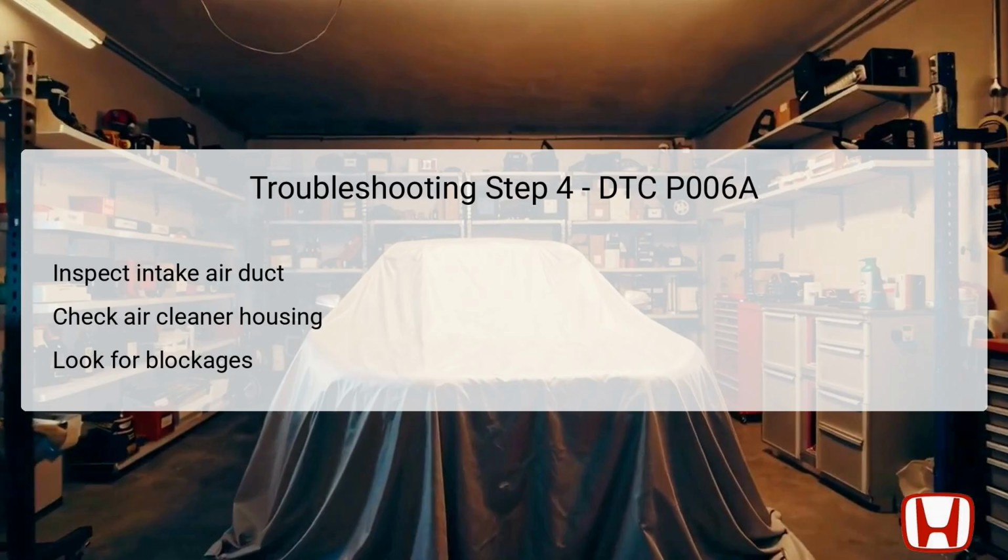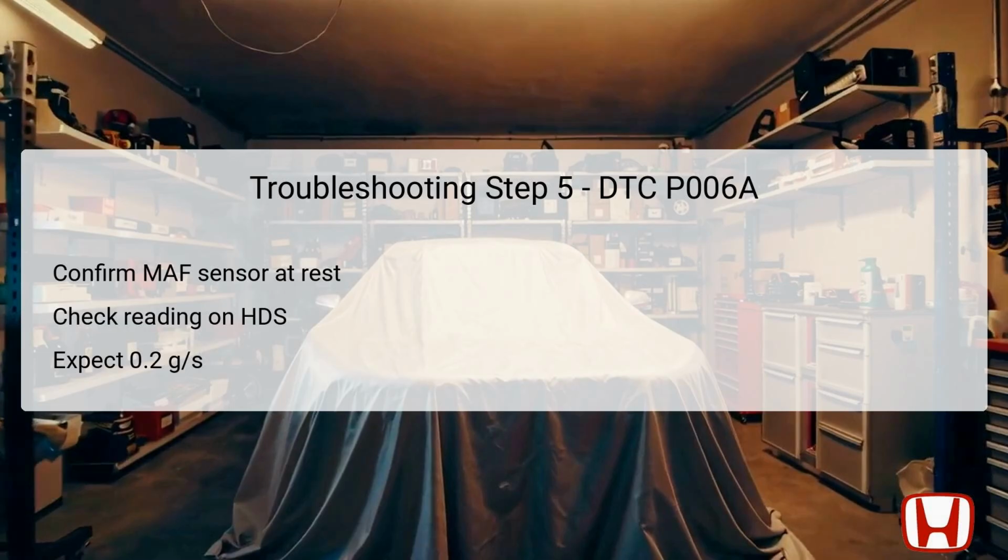Blocked or damaged components could disrupt the airflow, leading to performance issues reflected in the DTC P006A settings. Validating connections in the intake system will aid in confirming whether air can flow freely into the engine. Normal conditions dictate that all components are intact and without blockage. Finding any issues in this step may indicate broader problems within the intake air system, necessitating repairs or replacements as needed. The next step involves functional testing of the MAF sensor while the engine is turned off.